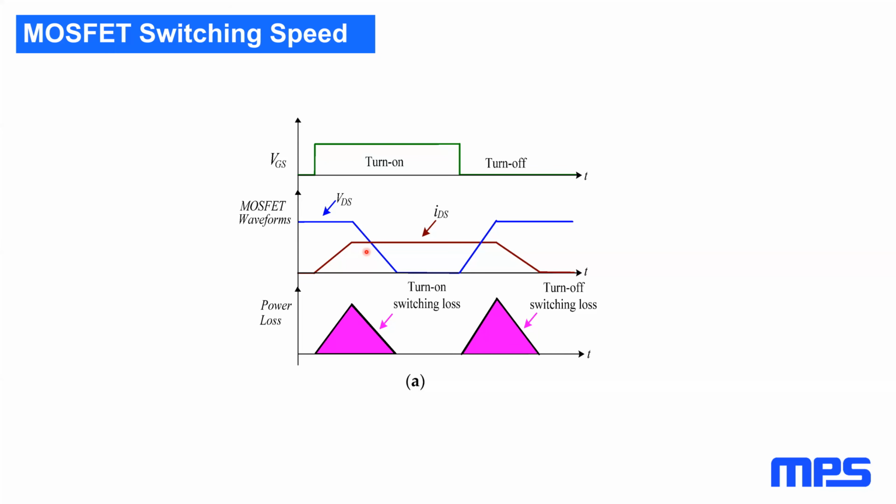Okay. And then it looks like our last one is how does the driver IC output impedance affect related power MOSFET driving? So the driver IC impedance is just in series with any series resistance you have in the gate. So when I talked about series resistance in the gate, in reality, that series resistance needs to be added to whatever impedance the driver IC has.